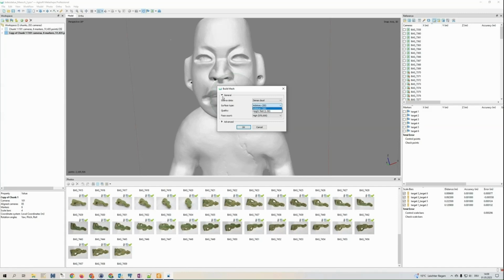For a complete 3D object, the setting should be left as given. However, the face count, meaning the sum of individual surfaces, should be set to high. Reducing the surfaces only makes sense if you are working on a very weak computer. We can color the geometry directly by selecting Calculate Vertex Color.